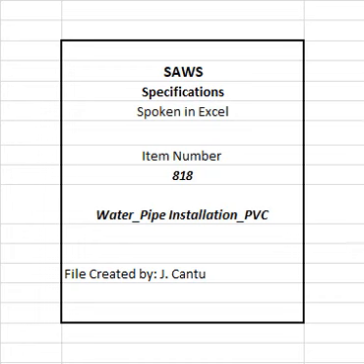Minimum pressure rating for all pipes shall be 235 psi, or as identified in plans and bid documents. 7. Pipe shall be DR18 pressure rating 235 psi. 8. PVC water pipe shall be blue in color. White PVC pipe is not permitted. 9. Only PVC pipe for 4-inch to 24-inch pipe sizes shall be used.